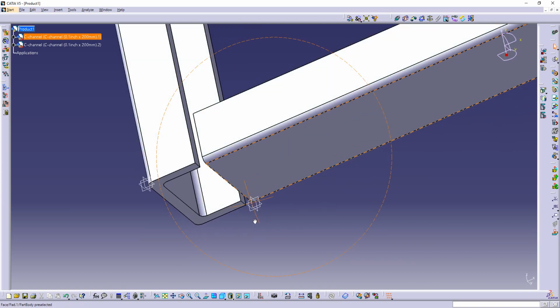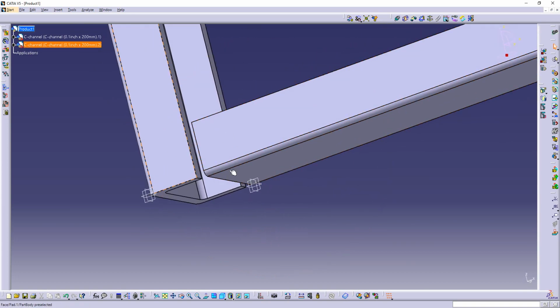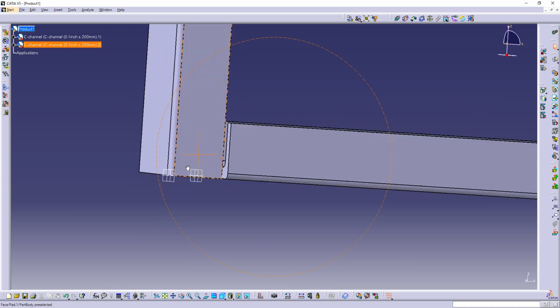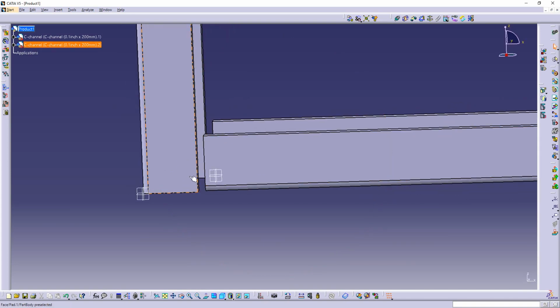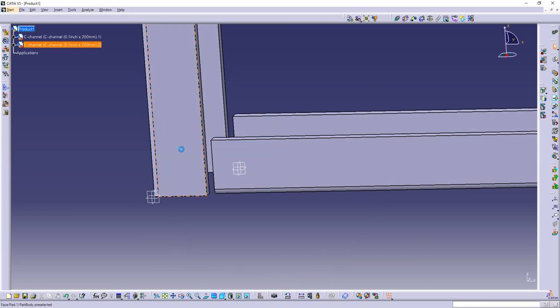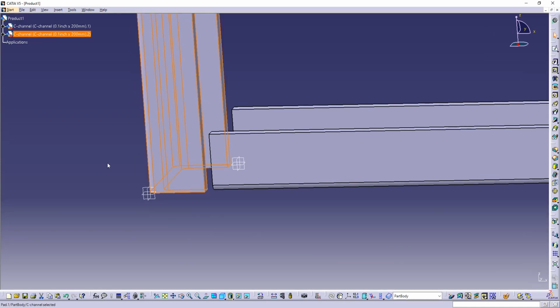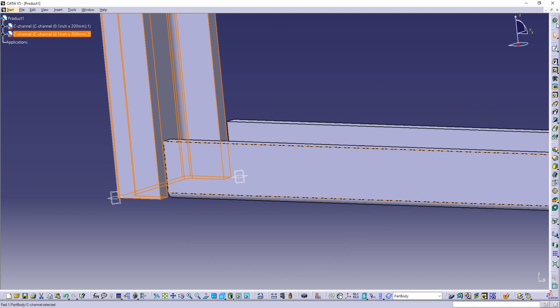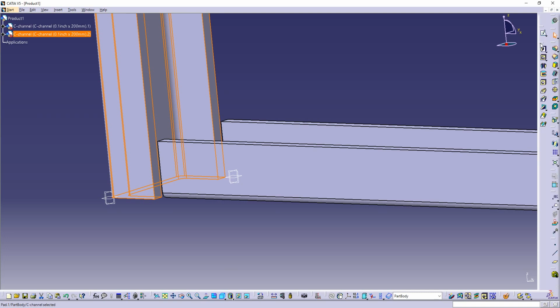And then I want to actually attach these two. To attach these two, I need to cut. For example, if I cut from here to here, I'll need to make sure that this side also is cut with the same angle and size. To start with that cutting, I will just choose the model here and double click on this. When you double click on this, you will see that in the assembly window, you are actually now transferring to a sketch or part design.